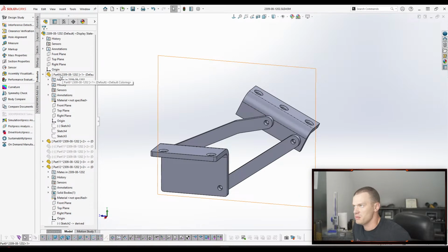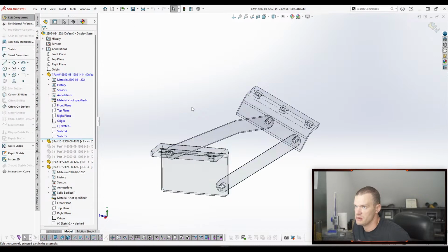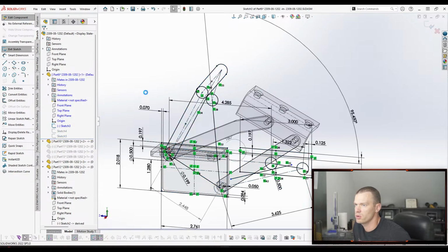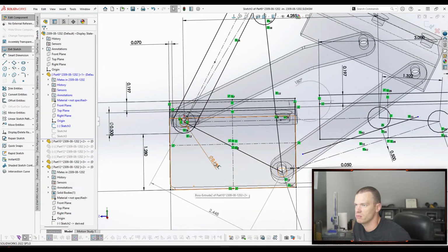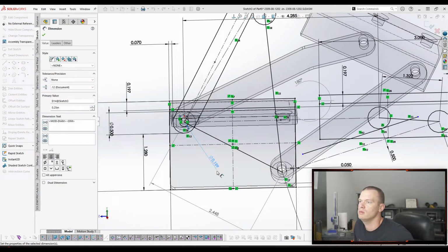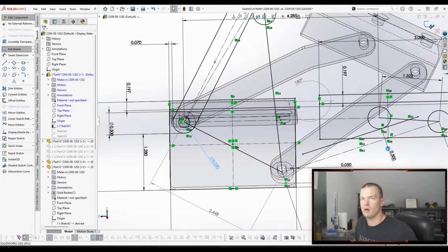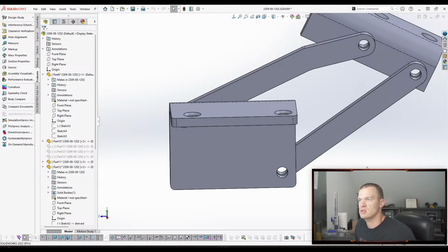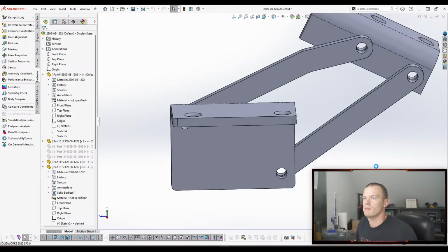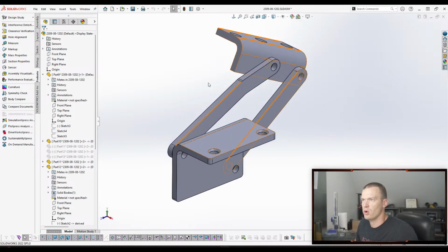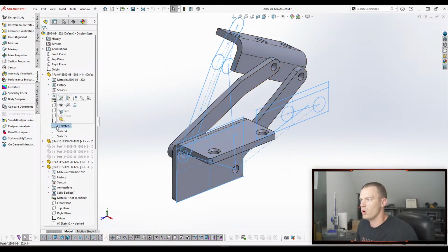If we wanted to change something, we could just come in here, say we wanted to change the through hole for the spacers. I'm making it all 1/4 inches for the rivets. You can see that it's already changed, right? So now they're all 1/4 inch holes. And that changed 4 parts instantly by changing 1 dimension in 1 place.